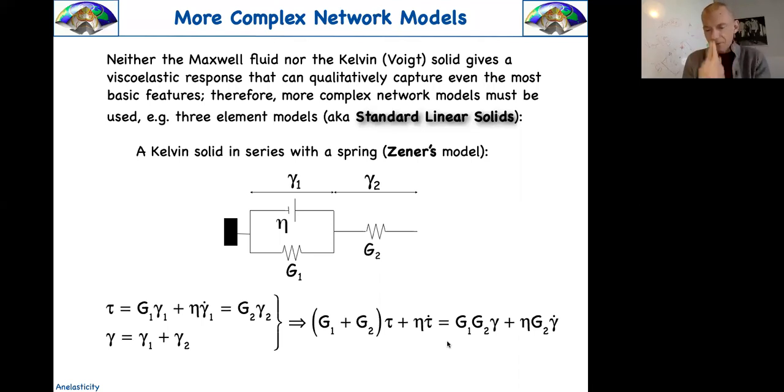And this is the message to take home. A standard linear solid is the simplest rheological model where we have now all the terms. What I mean here is that we have stress, strain, and stress rate and strain rate. Please do remember that for Hookean elements, typical in rheology, we have no time. And actually, it's this one, this and this. On the other side, the viscous element will appear in the rates, and here they are.